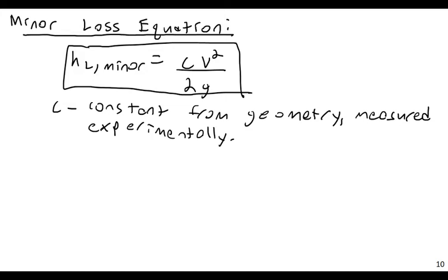Well, you create some pi terms, you run through a bunch of tests, and you basically figure out that G is always going to be the same, and you use velocity as your independent variable. Based on our experience with other minor losses, that's going to be proportional to velocity squared. So you run an experiment, you run different valve sizes through different kinds of velocity profiles. You measure the losses based off of some pressure measurements to the left and to the right of the valve, and you can actually fairly easily directly measure these C coefficients. It's really not that difficult.